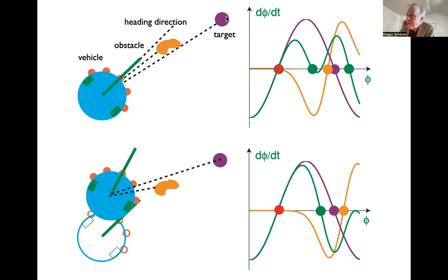The target is further away and, in terms of angle, it's on the right of the obstacle. And the vehicle is initially heading a little bit to the left of this obstacle. So here, the obstacle contribution makes this repeller, and the target makes an attractor that's a little bit to the right in angle. Now, again, with that trick of the obstacle, here's another sort of semi